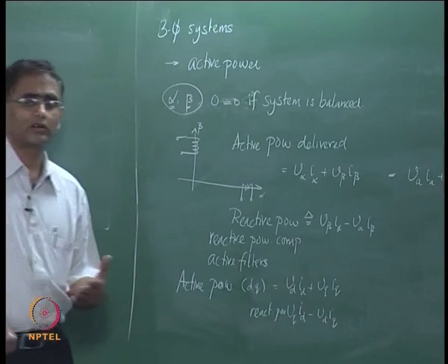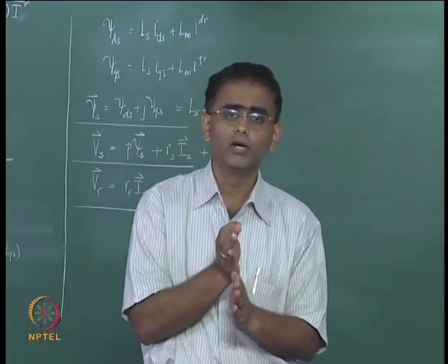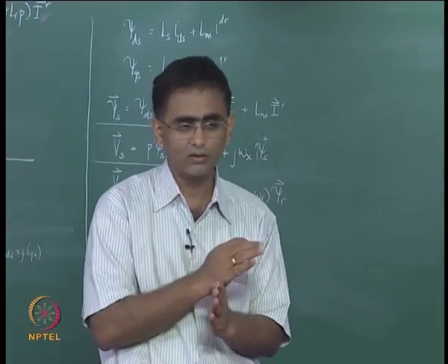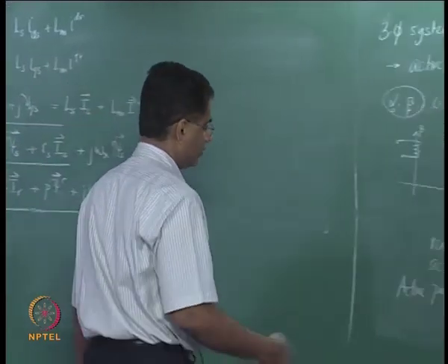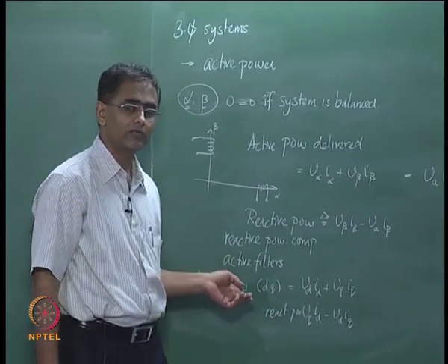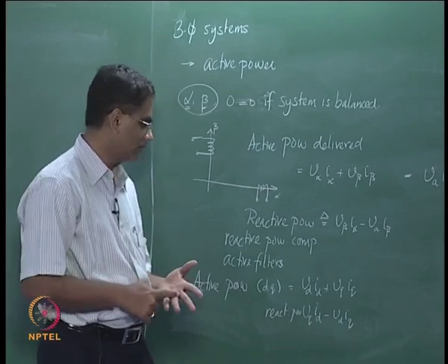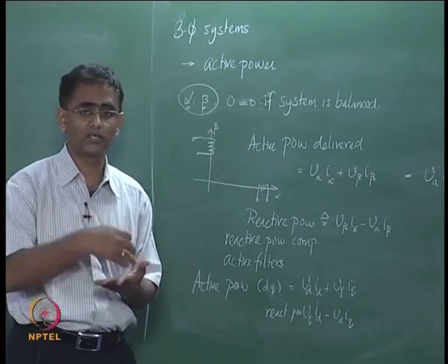Now because the synchronous reference frame is a rotating reference frame and you can position your D axis wherever you need, you can choose to have your D axis aligned with either the space vector of voltage or the space vector of I, or you can choose to have the Q axis aligned with them.